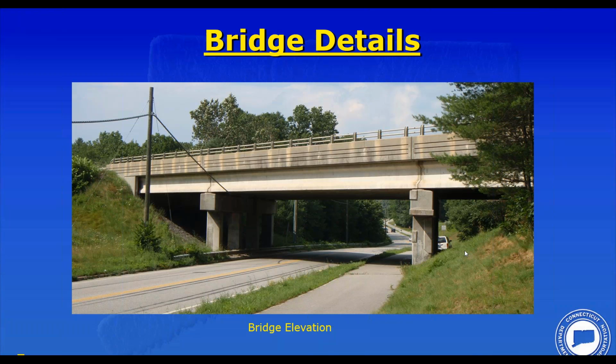However, as bridge engineers, we all debate whether or not a concrete bridge is more durable than a steel bridge. And the answer is, if you have leaking deck joints, it almost doesn't matter whether it's a concrete beam or a steel beam, you could have problems. And this is a great example.